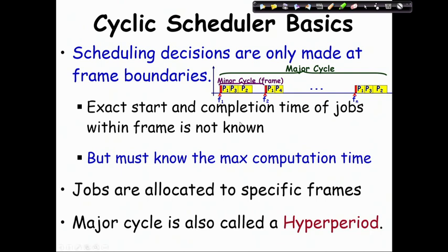So, one important thing to notice is that compared to a table driven scheduler, where the timer was set again and again, requiring much overhead, here that is overcome. The periodic timer is started only once during the initialization of the running of the system.